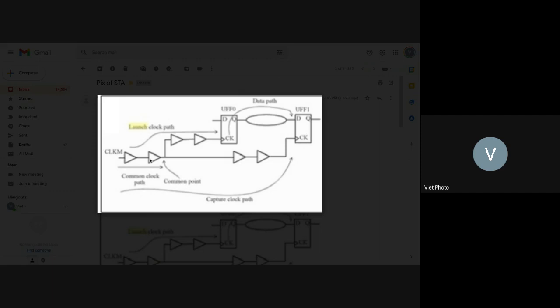So whatever it is here, the clock here, this part, right? If the delay of this flop, the cell changes, they all change together for this, right? So let's say if you have this the same, and this one here goes all the way to here instead of this thing, right? Then whatever this one, we don't care, because whatever is changed here is still the same for these two, right? The key thing is the relationship between these two clocks. And the difference between the two clocks here is determined by these two cells and these two cells.